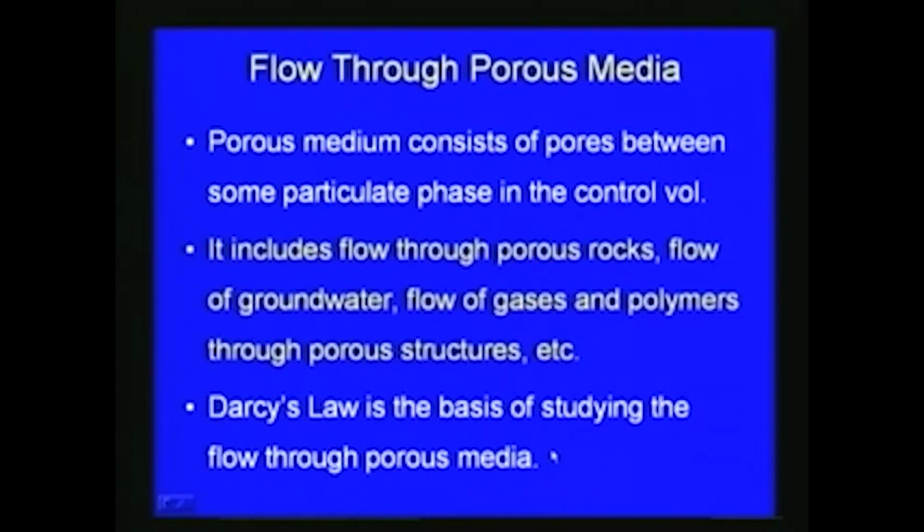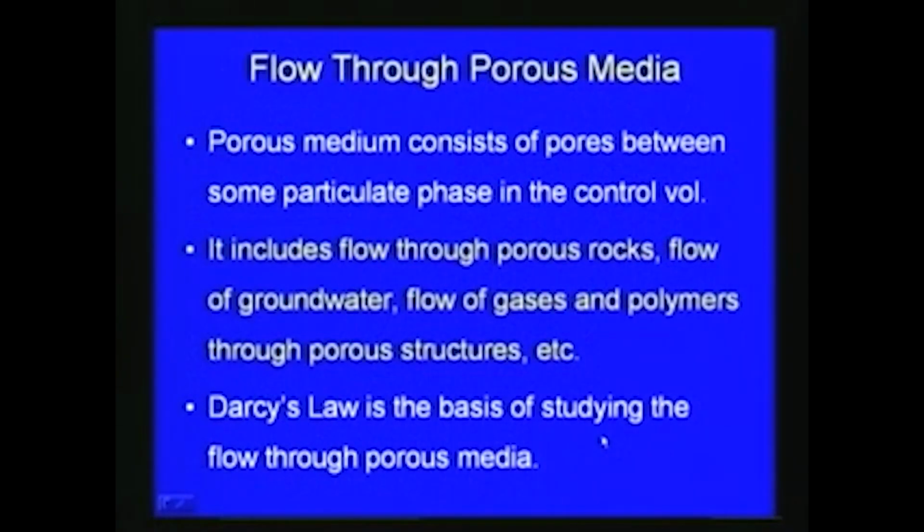Darcy did this experiment through porous media, and he showed that the velocity of flow is proportional to the hydraulic gradient. So, Darcy's law is the basis for the study of porous media flow. It has a number of applications, like groundwater flow and flow of gases and polymers through porous structures, etc. A number of applications are there.